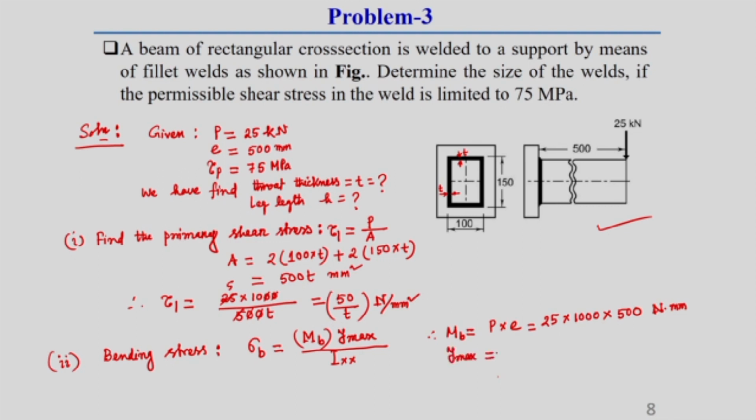This is the main step of this weld. Here we should consider the farthest weld's perpendicular distance between two axes. This is the farthest weld. Here you can see this is the CG of the whole weld; it is a rectangular cross section, so we can easily find it.